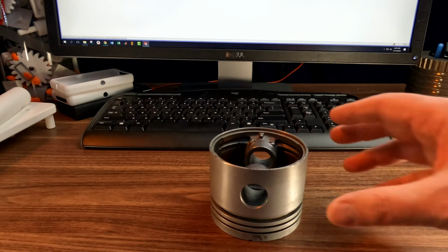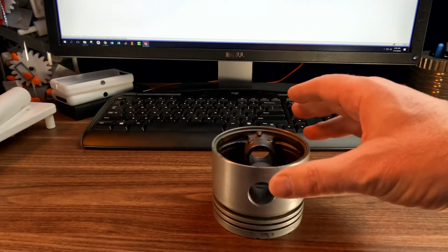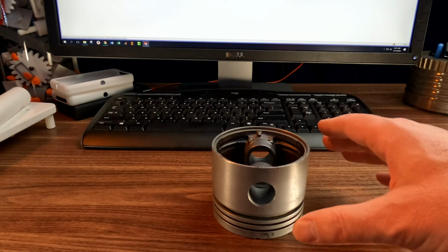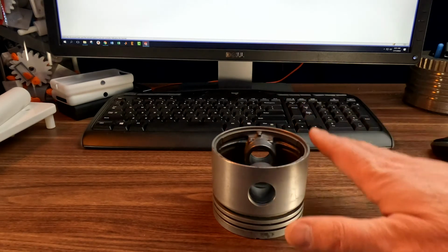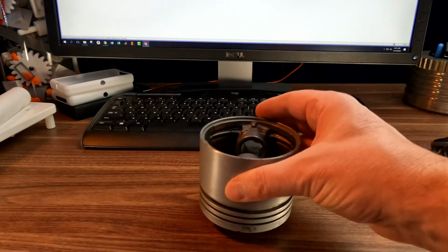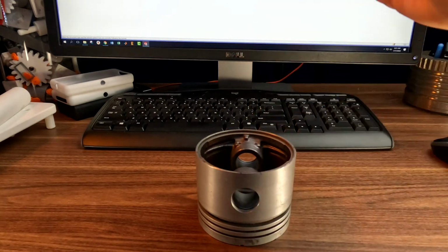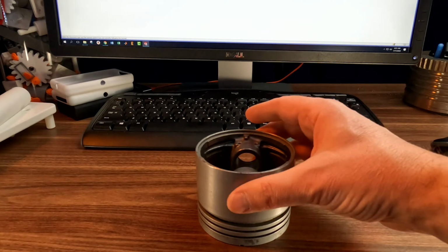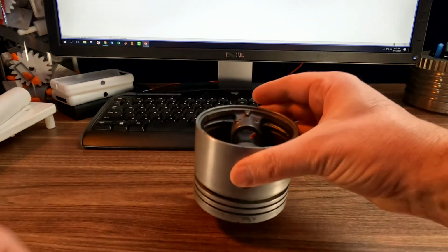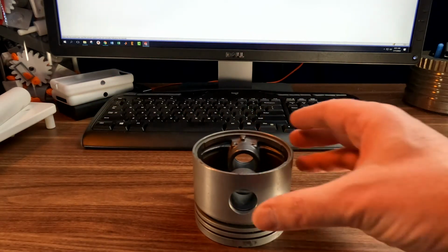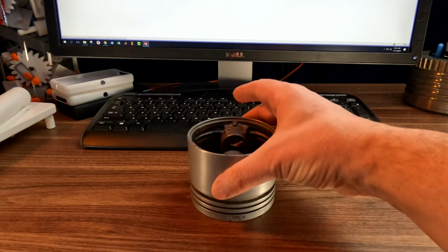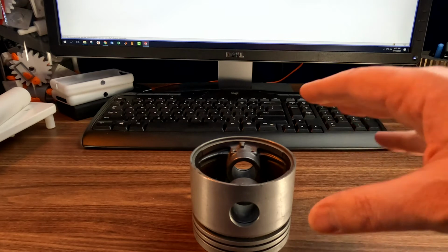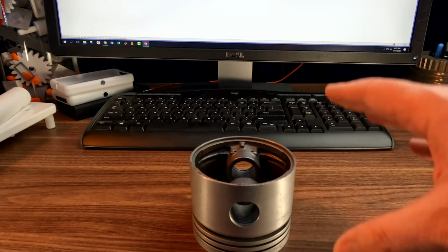Now, it's important to know that when we do an assembly mate like that, more than 1 degree of freedom might be reduced. So, for example, when I have mated this surface to this surface, no longer is Z translation allowed. Z translation is fixed because this face and this face have to be together. Now, I can still translate in X and still translate in Y. But there are 2 other degrees of freedom that are reduced with that single assembly mate.